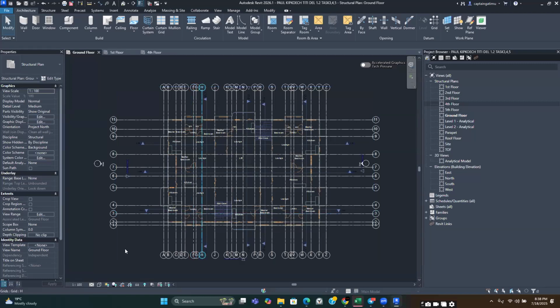Say you just draw two lines somewhere, and then you provide annotation to say these two lines represent a beam of say 200 by 450 mm. This rectangle represents the cross section of a 200 by 500 column. And like that, here we are going to be using live members that we can make changes to, that we can edit, and they store a lot of information.